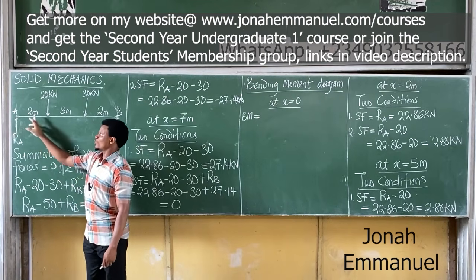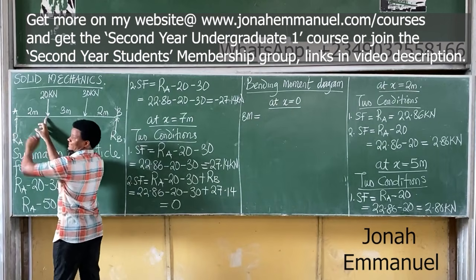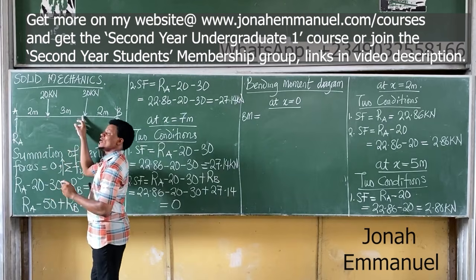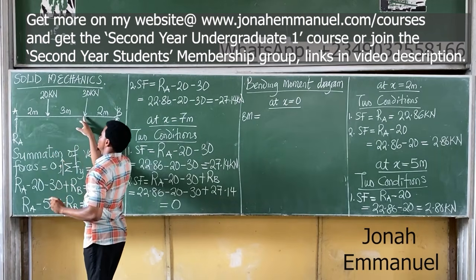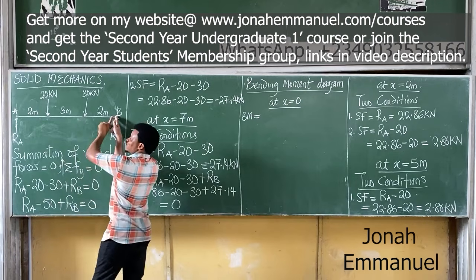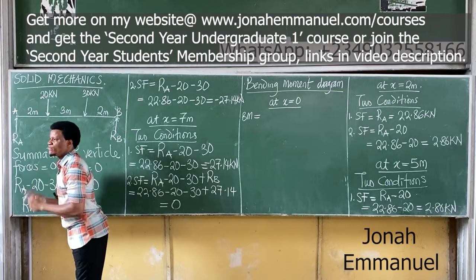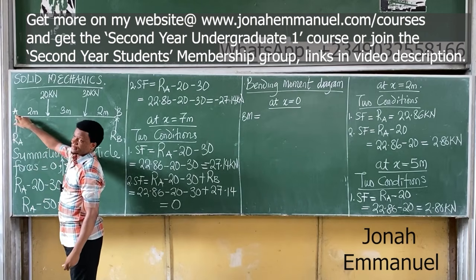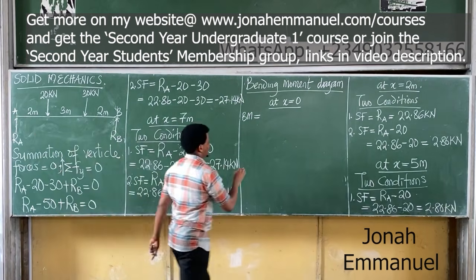At x equal to 2, we considered only the forces on the left-hand side. At x equal to 5, we considered only the forces on the left-hand side. So until the force passes you, consider this side. That's the concept. Let's use the same concept for bending moment. At x equal to 0, what force do we have here? RA. We have RA there.